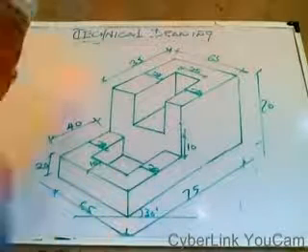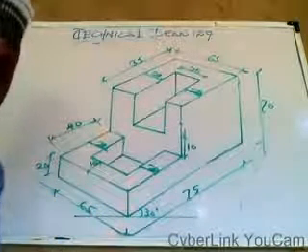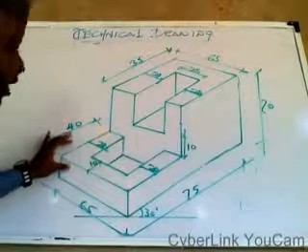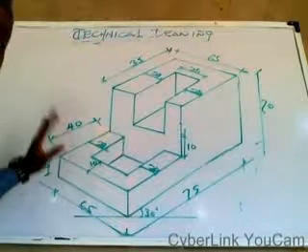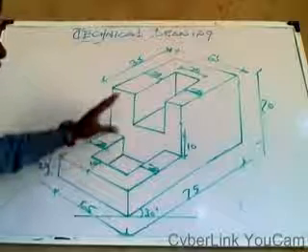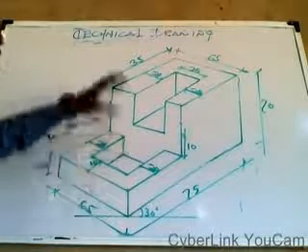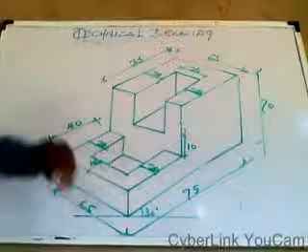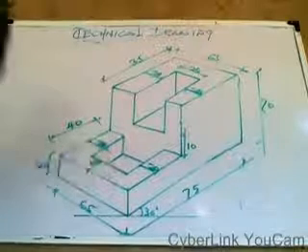One important thing is that after the diagram, you must make sure that you first of all start the drawing with faint line. That's the first step. After the faint line, and you have corrected all the mistakes, you have drawn the accurate drawing. You now outline it with bold pencil.